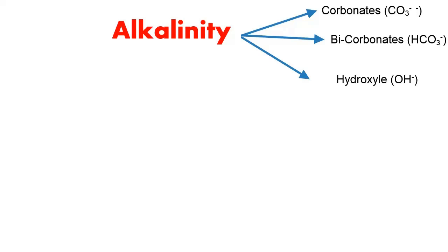Okay. When we add alum to the water, the water should be alkaline, that too with calcium bicarbonate. Understood? Alkalinity due to bicarbonate, alkalinity due to carbonate, alkalinity due to hydroxyl. Out of these 3, alkalinity due to bicarbonate and alkalinity due to hydroxyl should be there in the water for this reaction to happen. If it is not there, then you need to make that happen.